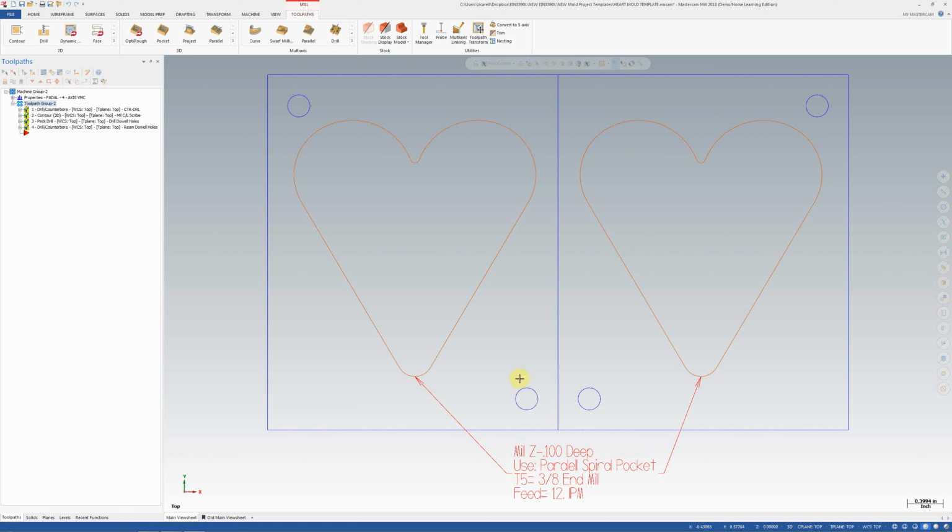They can't just be a drilled hole, because we're going to be press fitting some 1/4-inch steel dowel pins into each one of them. For that to happen, it takes 4 different tools for that to do the complete operation. We're going to be center drilling, which is going to make a spot mark in each location.